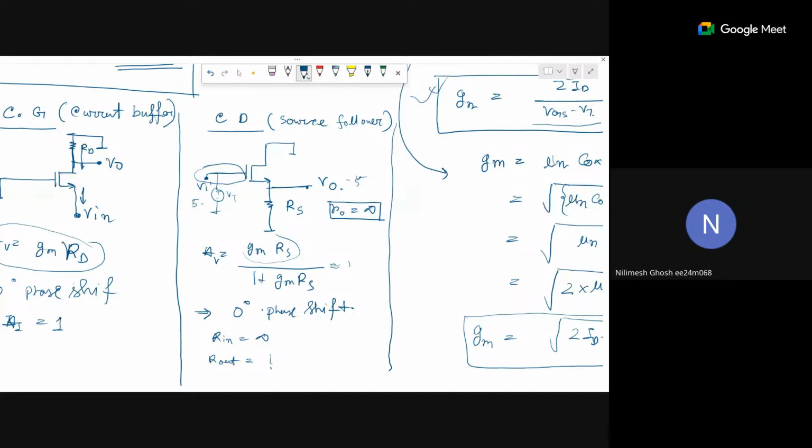You should replace all the source voltages and currents by their internal resistances, consider the small signal circuit, and calculate the current that flows from that test voltage. That test voltage divided by the test current will be your output impedance.